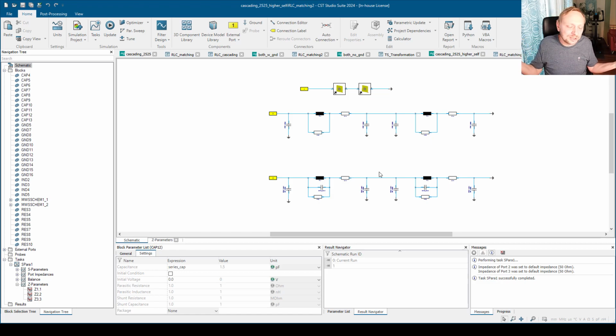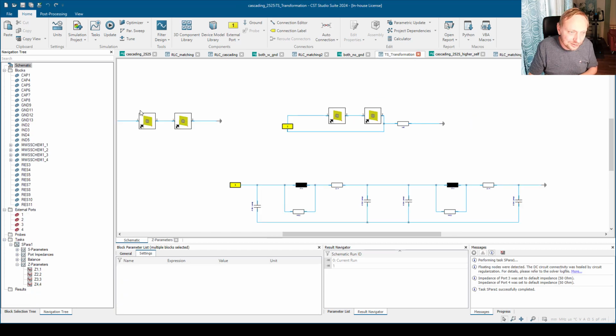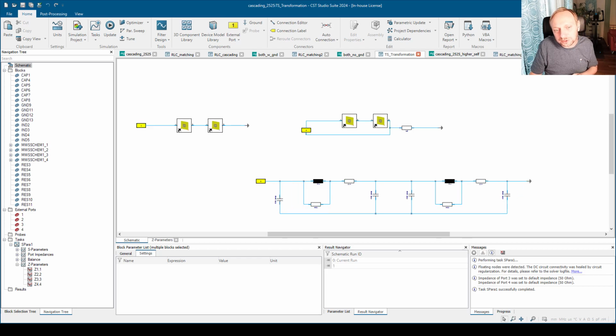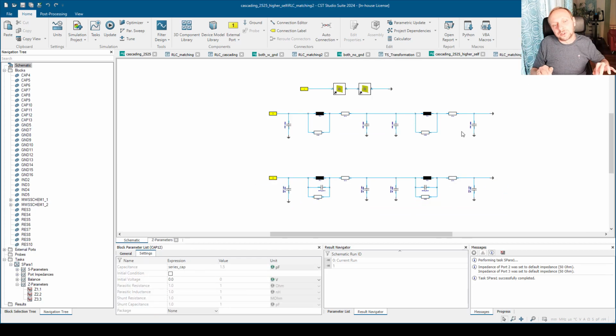And then this can lead to something a little bit confusing in the end. But putting it into one sentence, S-parameters are great, they work, but sometimes you need a little bit more time to understand what they do on the circuit, and that's exactly what I try to show here. Don't get confused by this transformation thing here. Maybe if you didn't understand this, the most important thing is if your equivalent models are correct and contain everything which is in the Touchstone file, both will work.